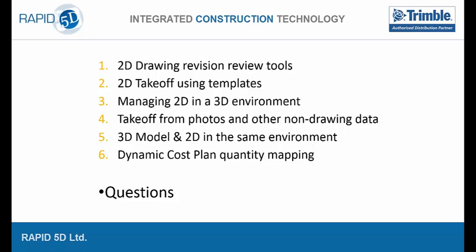You could take some bulk quantities from your model, say your concrete walls, and then take some things from your drawing. Say you do a count of the FFE in the drawing, or, like I did in the photo, you take some existing counts, and then map that into the cost plan, and then you can apply manual quantities as well. So you've got prelims, you've got craneage, you can just add that into the cost plan as manual quantities.